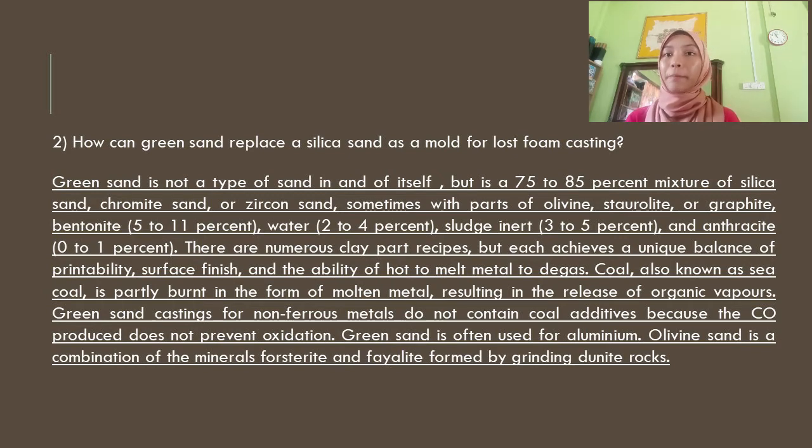There are numerous clay recipes, but each achieves a unique balance of printability, surface finish and the ability of the molten metal to degas. Coal, also known as sea coal, is partly burned in contact with the molten metal, resulting in the release of organic vapors.